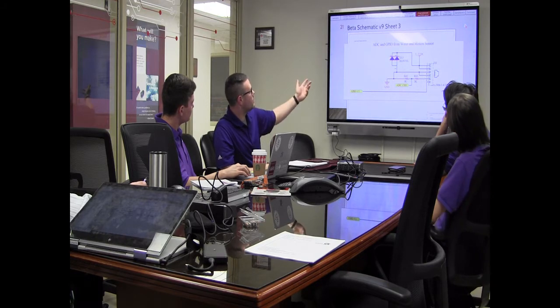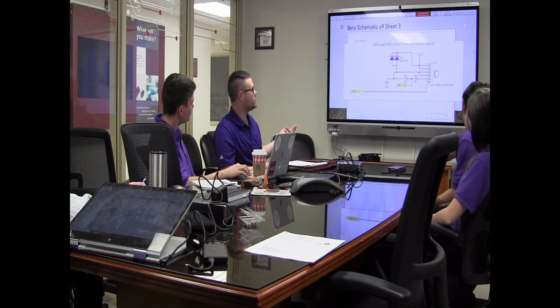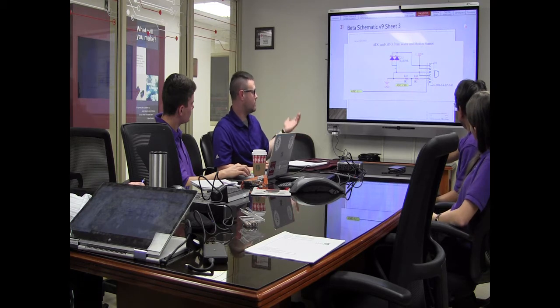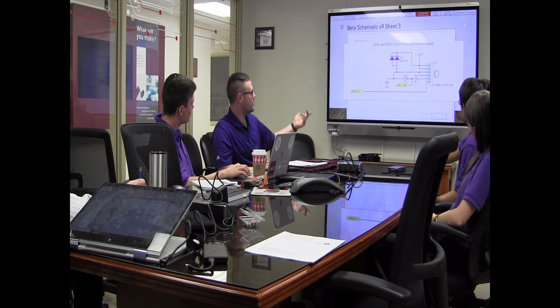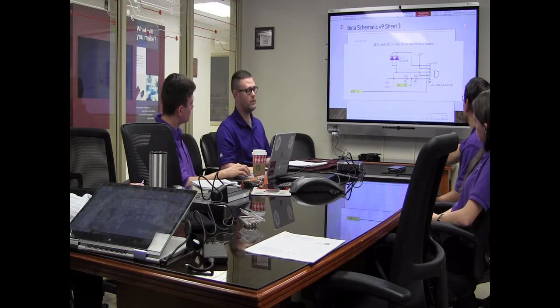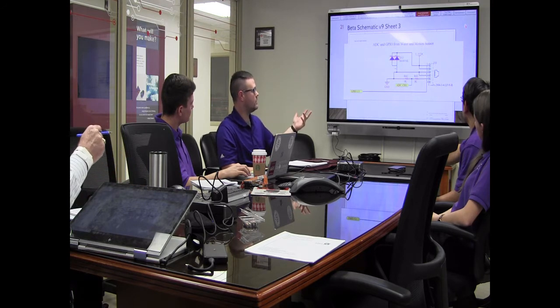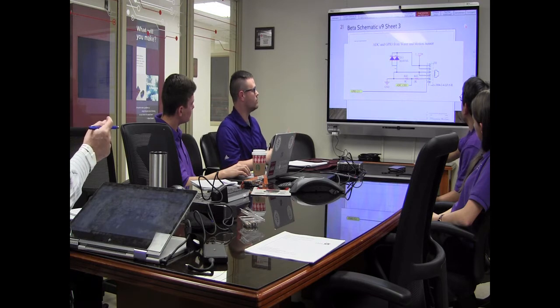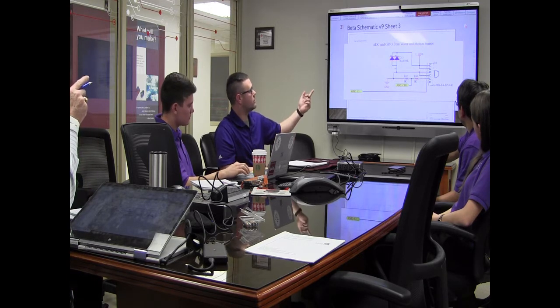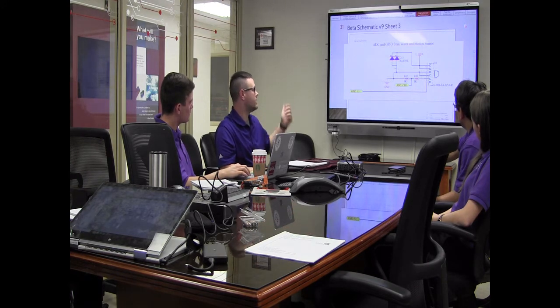Well, they could be. So here's our ADC and GPIO from our water and our motion sensor. On pin 6, you've got our motion sensor, which just uses a simple digital high and low. And then on channel 5, you can see the voltage divider. Because the voltage coming back from our water level sensor is basically double what we needed, so we just cut it in half so that the ADC, which doesn't have quite the 3.3 volt range, it's more like 1.6, 1.8, can handle the values that it's seeing. So we can actually measure the depth of the water if we need to, as well as 3.3 volts with ESD protection, I guess, going out through a